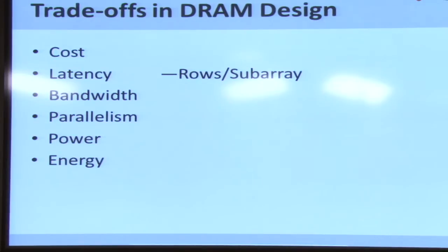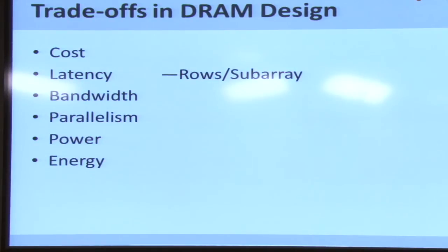Exactly, right? So just before the data is sent out on the memory channel, there is a register where it stores the 64 bits that it's going to send out in the next 8 cycles. Everything above that operates at 4 times lower frequency. Everything below that operates at bus frequency. Yeah. So why not get 512 bits and then send out 64 over the next 8 cycles? What's the problem? You tell me.